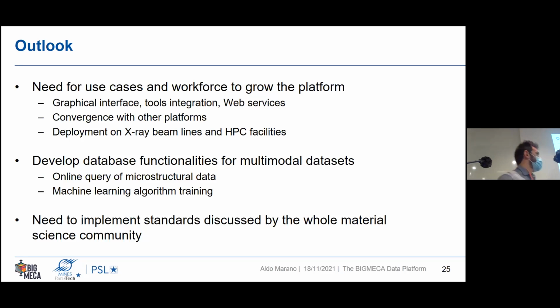Yeah, well, I think that the way to go is to focus only on the HDF5 file, and as I see it, we only use the XDMF extension, so it's better to say extensions, to get the ParaView compatibility for now in our needs. So maybe we need to work on a plugin that allows to read the grids that are formatted like this from the HDF5 file. I mean, it's the same thing. If it can get the information from the XDMF, it could get it from the HDF5 file because it can read it. So maybe that would be the way to go.